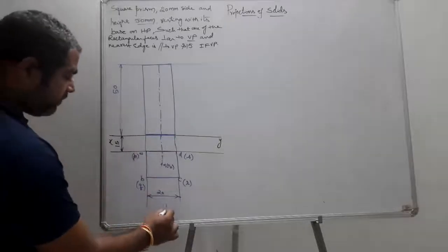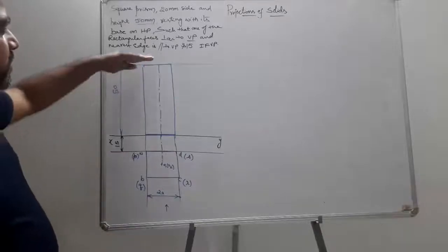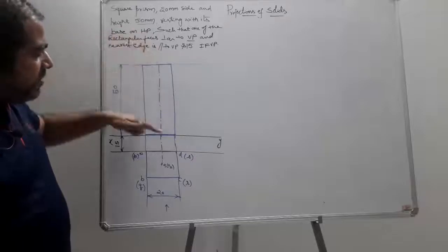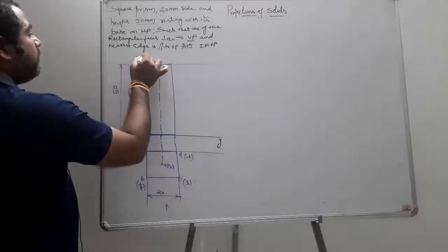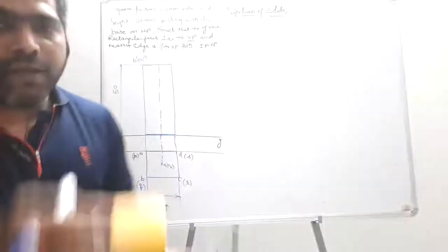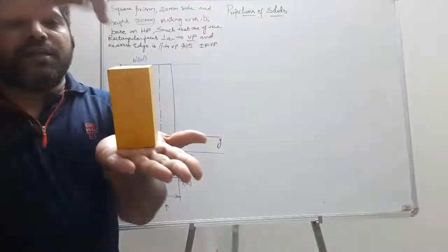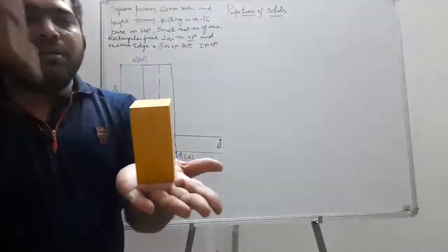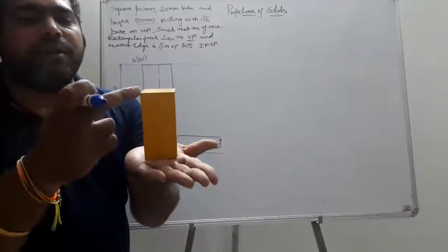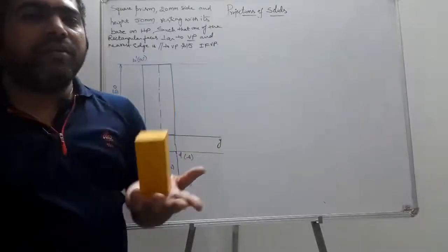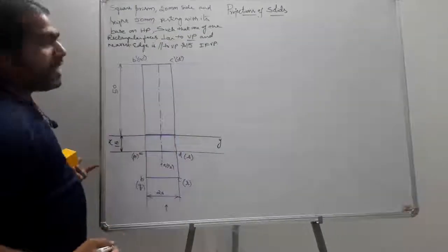When you are going to see from the front, let me tell you what the visible points are. Top is nothing but ABCD, bottom is PQRS. Top points are B dash of A dash. Why? Because here the prism is ABCD, PQRS. Top points are ABCD, bottom are PQRS. So while you are going to see from the front, B of A, C of D. So B dash of A dash, and similarly this becomes C dash of D dash.